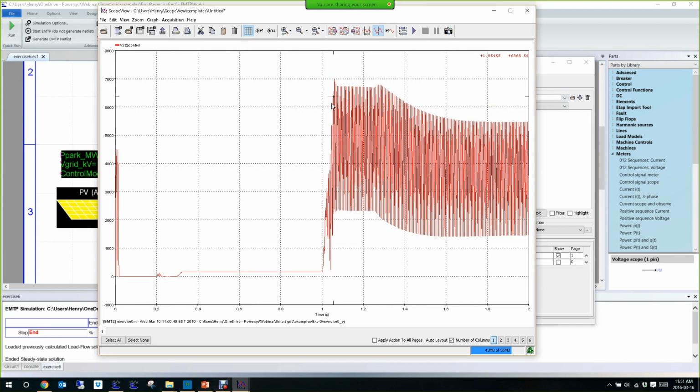You can use this one. Another method would be to try to change a little bit the frequency. When the grid is connected, it's impossible. When the grid is disconnected, it becomes possible. You have a lot of other methods. You can try to change the angle of the voltage, the magnitude. So there are different ways. This is one of them.